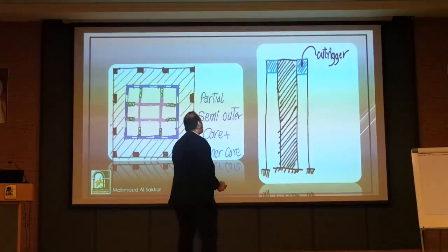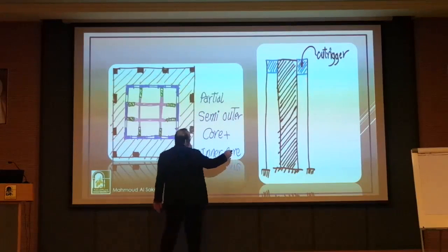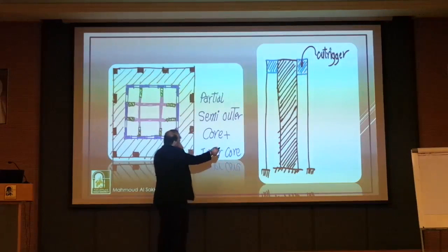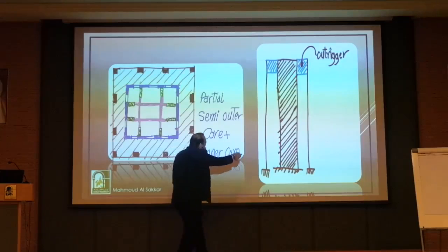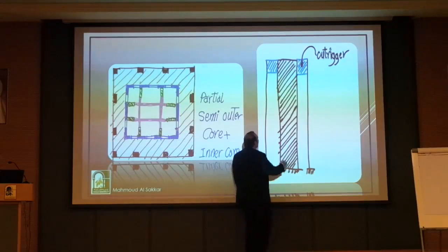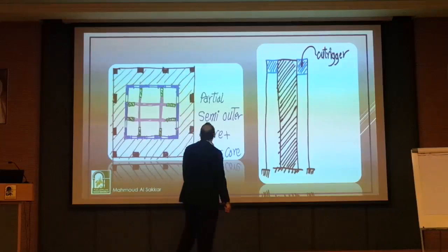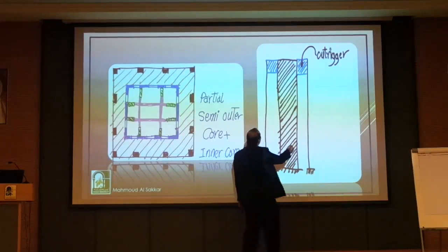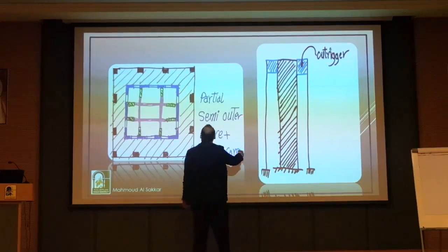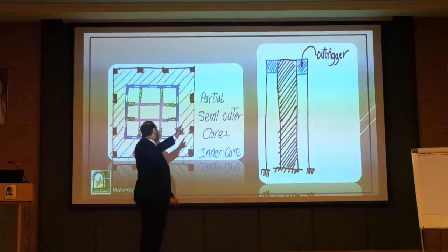Outrigger, okay? So we have the outrigger over there. It's going to be like a shear wall. Some people say this outrigger is not continuous over there. Come on, guys. It's not carrying shear wall. It's not carrying moment in that way. It's carrying the moment in the other direction. It's not carrying shear. It's not shear anymore. Okay, so outrigger.